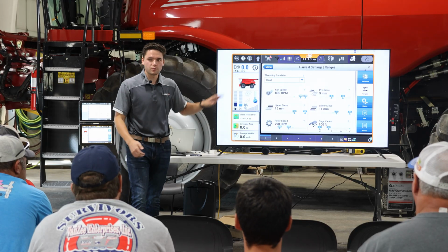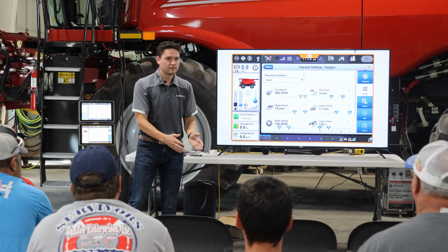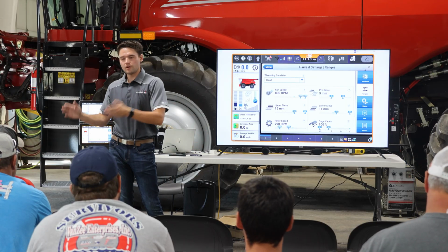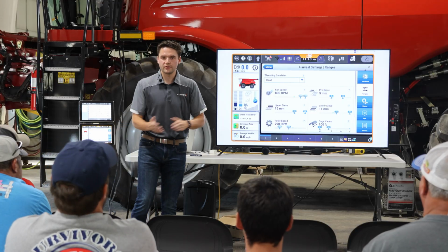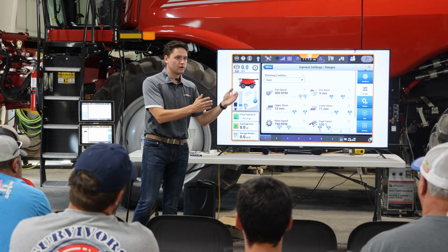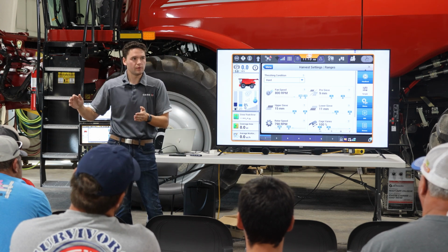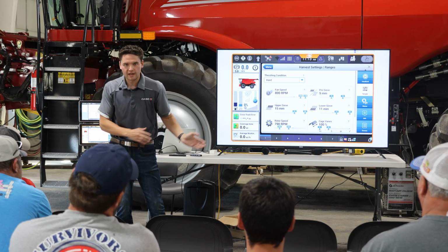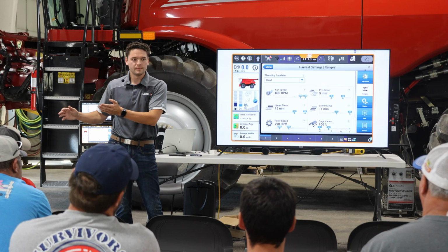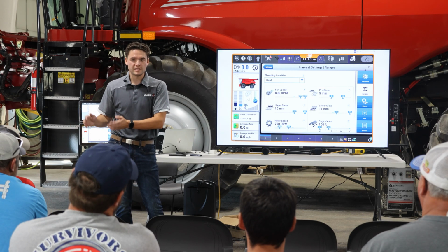By making this change, we're just changing predetermined ranges or limits on the machine, saying that this crop is hard to thresh. So when you are testing, figuring out which set point works well, don't test the settings that we would normally use in easy and medium threshing. Don't even test those. You're not allowed to even go in there, because I'm telling you it's not going to work right away. Does that make sense?